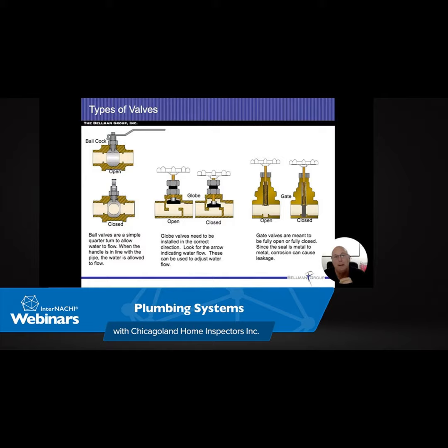All right. But I would like you to get an idea of how these pressure relief valves work. In a nutshell, there's two different devices. It depends if it's a temperature relief valve or a pressure relief valve. The temperature relief valve, that's that wax fill. We'll go to the bottom picture first. That wax fill that's there, they have different colored wax that gets in there depending on where this thing is going to be set. And when that opens, it stays open. So the wax changes size, opens the poppet valve, and then water will continue to flow coming out of there.